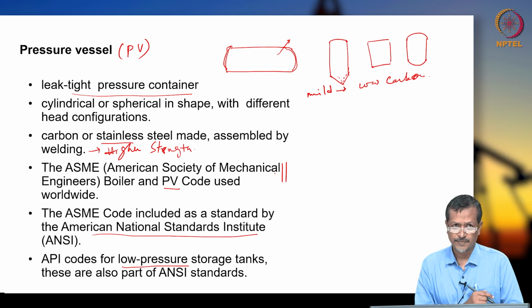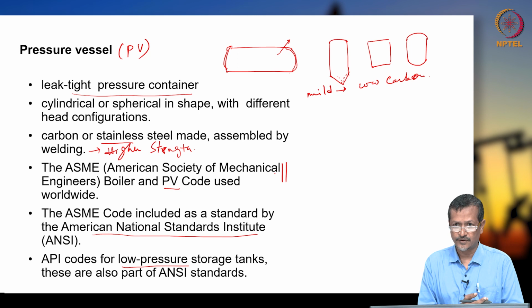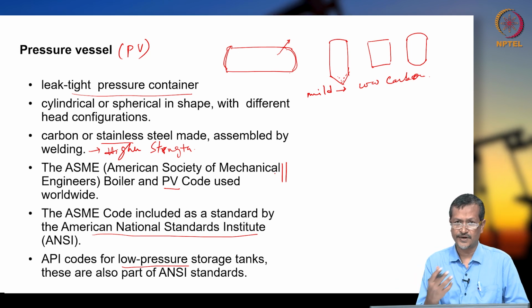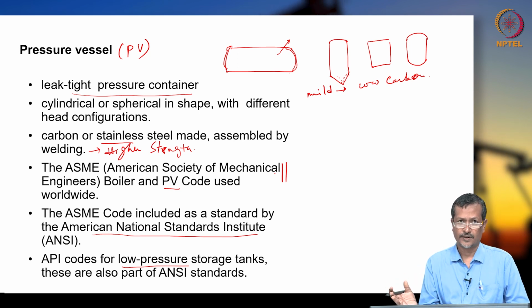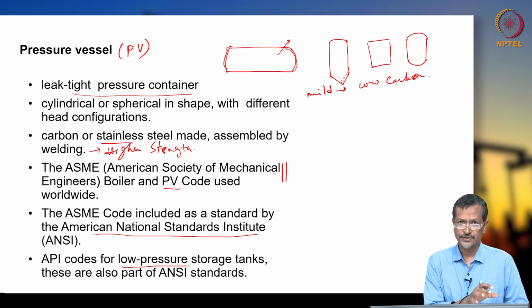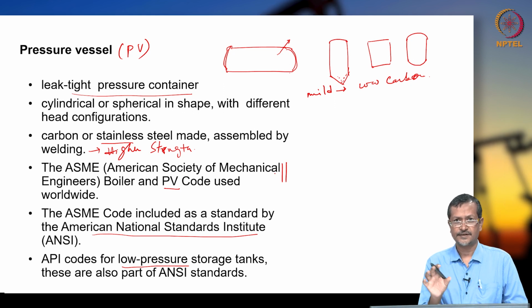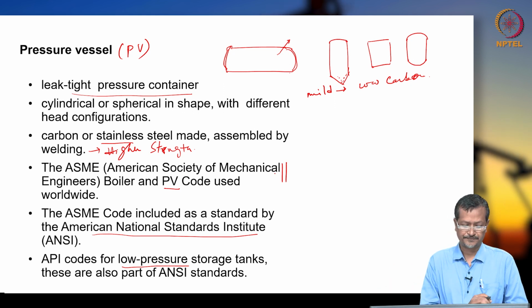If temperature is increasing, material property will change, because at high temperature the material will be creeping quickly, or it will be elongating, or the material property will change, and finally your system will not work. So you have to check temperature, pressure, and what type of fluid you are using, fluid properties you have to know actually. Based on that you are selecting, designing and operating the pressure vessel.